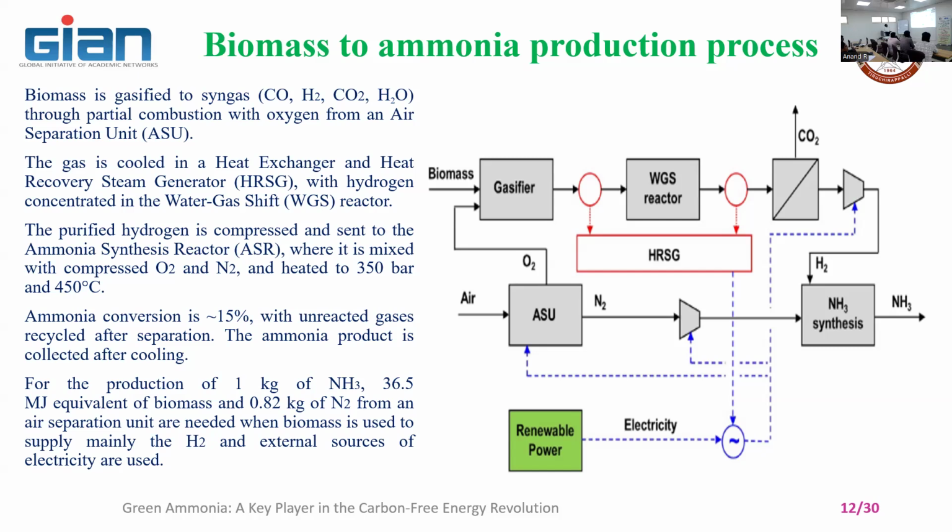Then the gasifier has several applications. The gases come out at different temperatures, high and low. If you are going for updraft gasification, you are going to take the gas at the top, and the temperature of the gas is around 400 to 500 degrees centigrade. So you should not waste it.